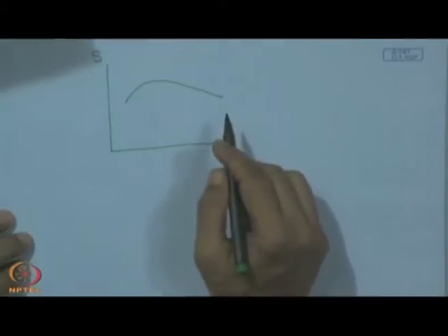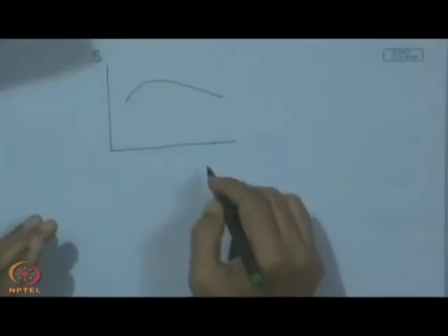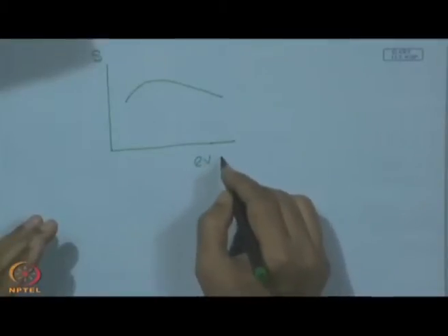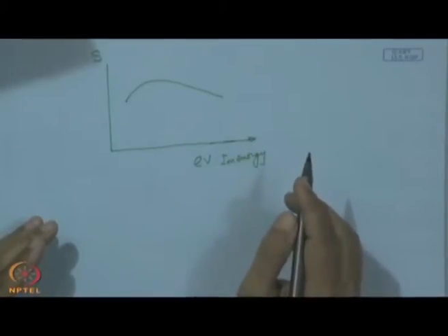That means, when we increase this discharge voltage, naturally what we try to increase is the ion energy. However, at the same time ionization cross section will keep on falling, and as a result this sputtering yield will also keep on falling. So, then it is not a very useful or fruitful method.